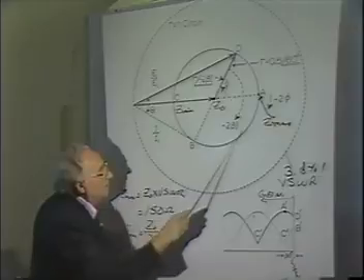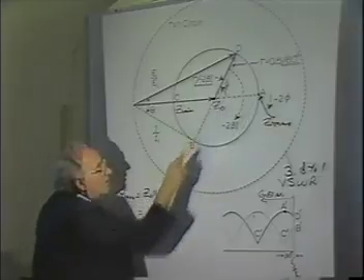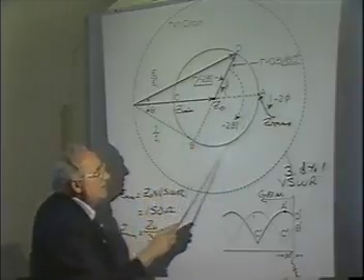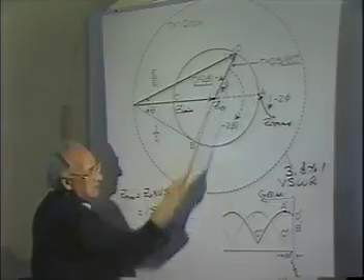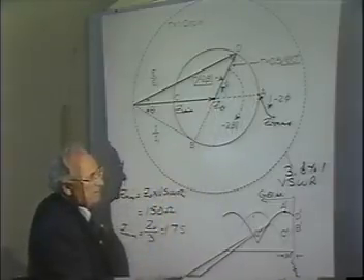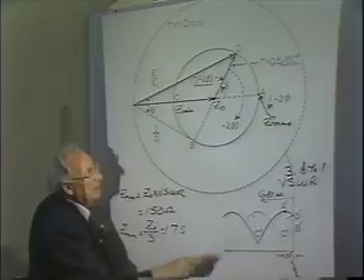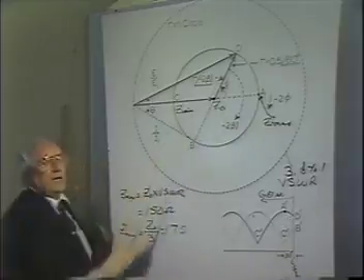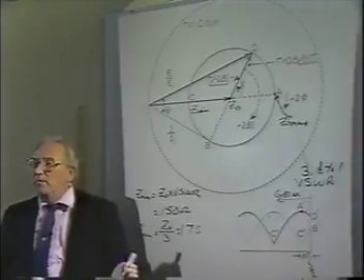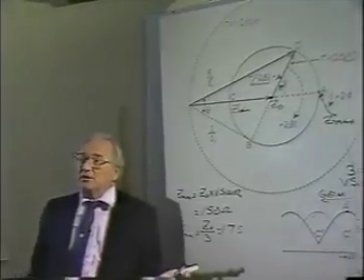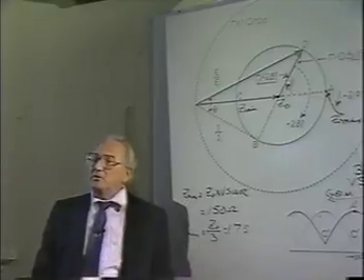Here, am I going back toward the load? Yeah, there's a load up here. Is E minimum, E maximum, back to the load. And here you have an inductance and a resistance in series. Now, if I cancel the inductance at that point, does that mean that I match the transmission line?